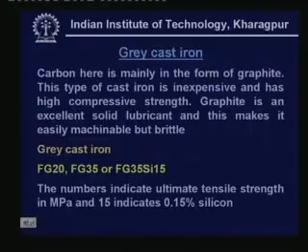Normally you find the yield point, then the material goes to an ultimate stress value, the maximum value, and then it ruptures, or fails, or the breaking point comes. The maximum amount of stress that the material can take is that ultimate tensile stress, and that is in MPa.